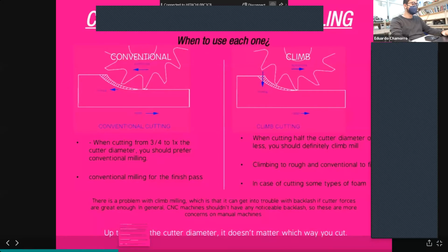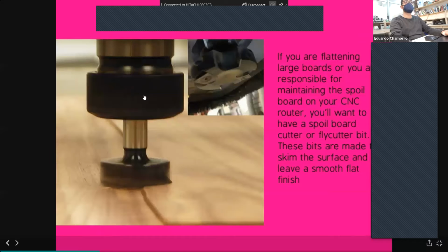It's the collet of your machine. Here, this is the collet chuck or the collet nut, basically a nut, that tightens counterclockwise. So if you rotate clockwise, even if you didn't tighten the nut well enough, it will self-lock. If your motor rotates the opposite way, it will tend to unlock. And this is something that you don't want to happen. That's why most of the machines rotate clockwise, so they tighten the nut on their own rotation. Just in case. Even so, you should never cut with a non-tightened collet nut.